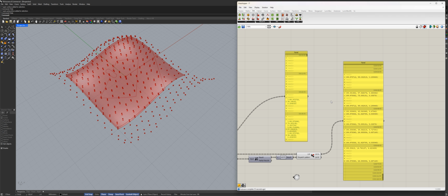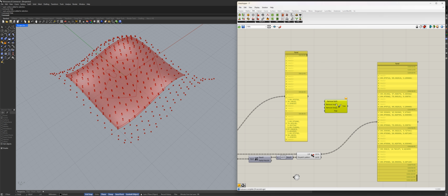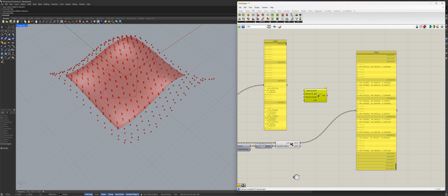Can I ask Grasshopper to remove all of this kind of junk? Yes, I can. For that, I will use the node which I briefly showed previously, very randomly, but never explained. This node is called Clean Tree. It sits under Sets, Tree, Clean Tree. Now this node works on the trees and cleans them up from different artifacts or elements. For example, it can remove empties, remove invalids, and remove nulls.